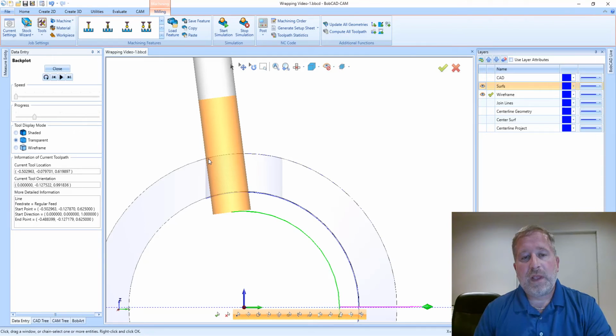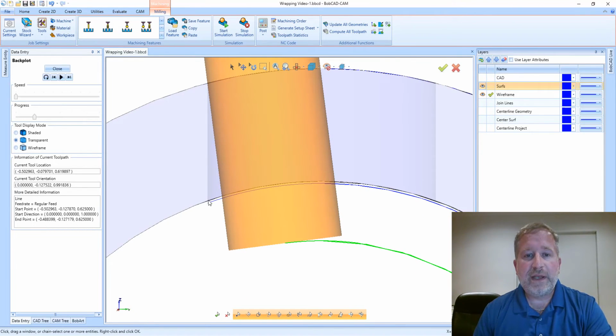that slot. Now, if we switch to a larger tool, in this particular case, the width of the slot is a 1/2 inch. So we would be able to switch over to a 1/2 inch tool and try to cut this slot. But I wanted to show you, this is the biggest confusion that people have about using a wrapping group, and that is a wrapping group is not a true 4-axis tool path where it's going to keep that tool and move it off of center line.